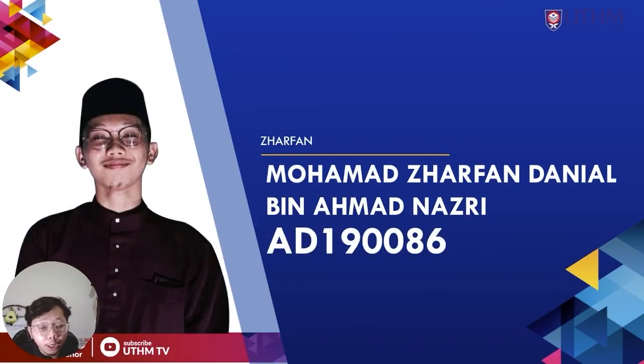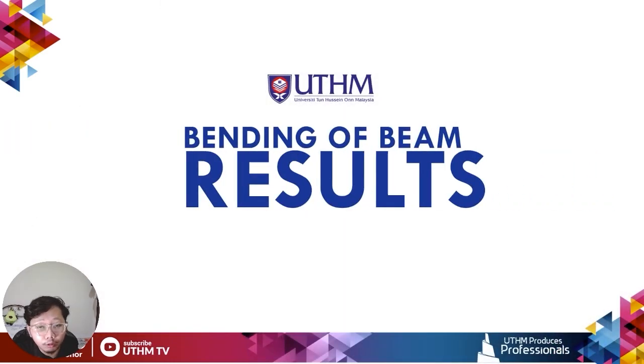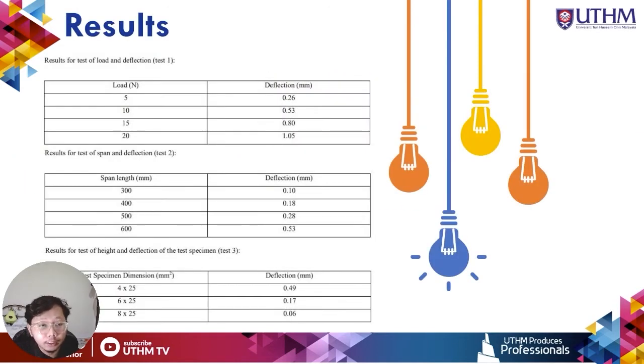Assalamualaikum warahmatullahi wabarakatuh. My name is Muhammad Zarfan Nabi Ahmad Azri with metric number AD190086, and in this video, I'm going to present the results and also the calculation of bending of beam. There are 3 results in the experiment. The first one, we need to find the relationship between load and deflection. These are the results: 0.26, 0.53, 0.8 and 1.05. The second test is to find the relationship between span and deflection. The span lengths are 300 mm, 400 mm, 500 mm and 600 mm, and the deflection that we got starts at 0.1.